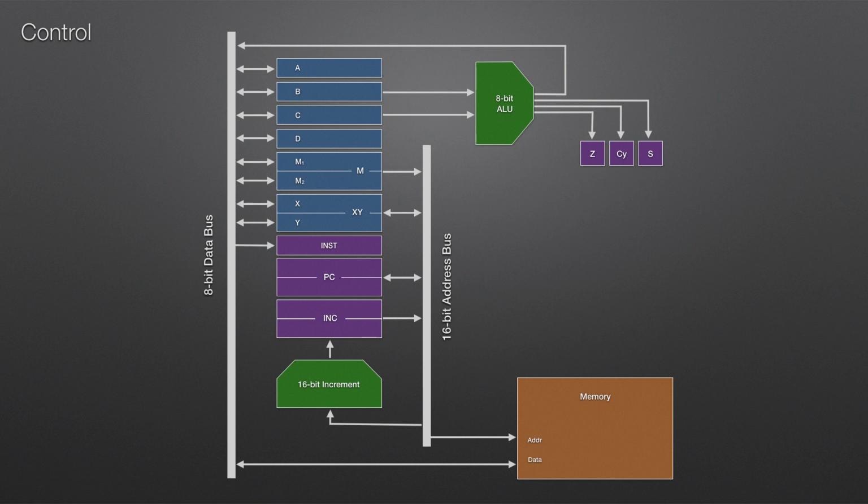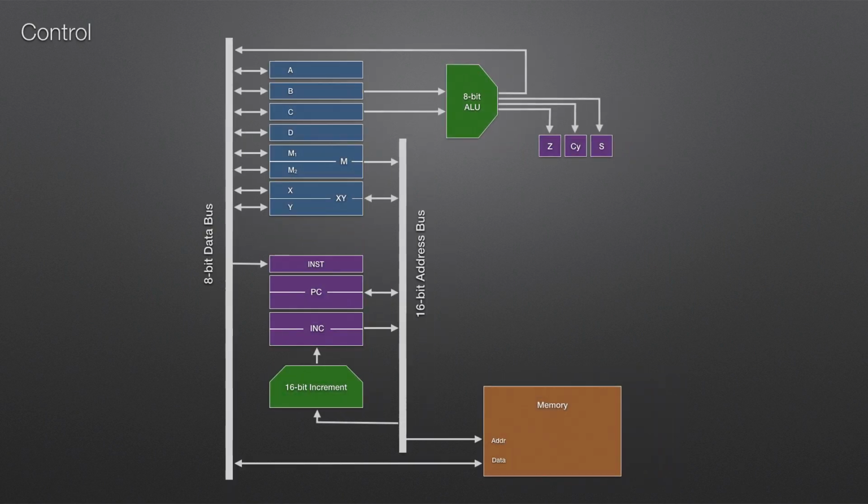Okay, so we've nearly got our architecture diagram complete, but there's just one final thing missing, and it's the thing that makes it a true computer in every sense, and that's the ability to do branching. So let's open the diagram up because we're going to put one last block into here. And this time it's going to be a J register. So again, just a 16-bit register made up of two 8-bit registers, J1 and J2. And again, a little bit unusual and specialised in that you can only load it from the data bus and you can only gate it onto the address bus.